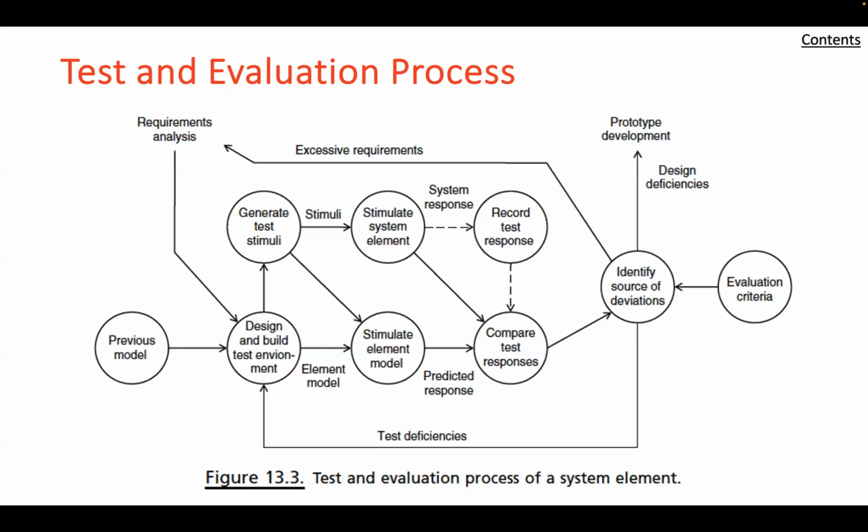Then we have the analysis and evaluation of the test results. The outputs from the components or subsystem under test are either recorded for subsequent analysis or compared in real time with their predicted values from the simulated element model. The results must then be analyzed to disclose all significant discrepancies, to identify their source, and assess whether or not remedial measures are called for. So there's a lot of details that go on in the development testing.